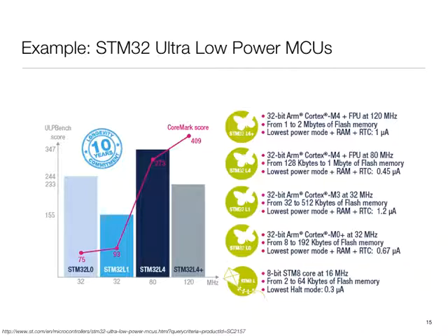The dominant reason why there's so much attention to memory is because when it comes to power consumption, RAM is extremely power hungry. Okay, so why is that? There are two types of RAMs, right? There are DRAMs and SRAMs. DRAMs use a single transistor to store the value, and if you are reading or writing it frequently enough, you don't need to do anything, otherwise you need to refresh it. But DRAMs are slow. Okay, if your processor is running at a few hundred megahertz, DRAMs are going to take many cycles to do it.